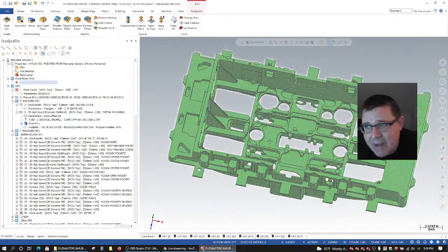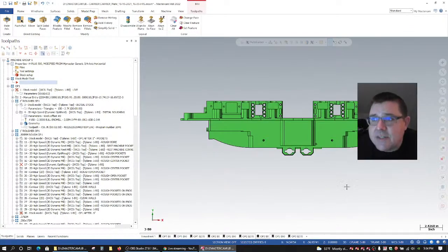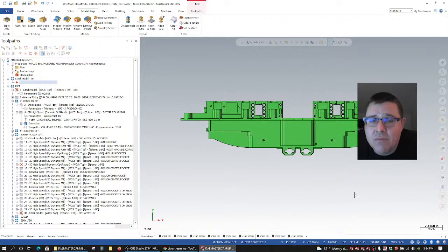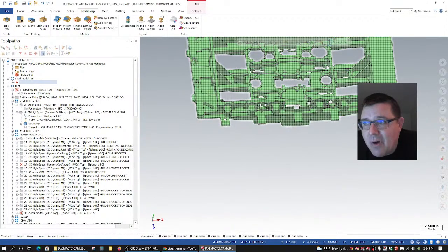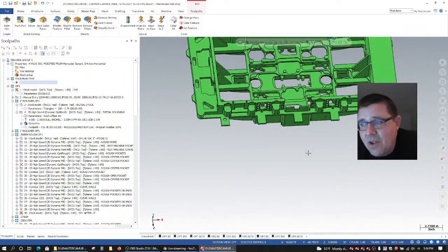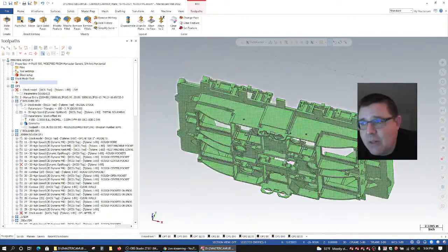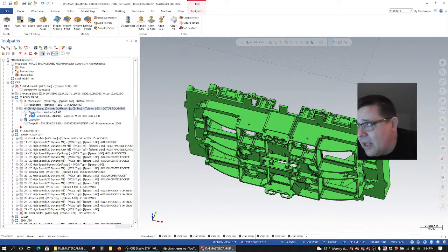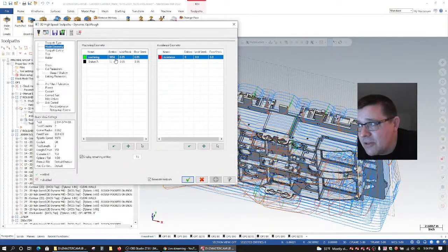What does this do for me in here? Okay, if my tool is coming from this view, this surface here, some of these other little surfaces, all of those are important. But anything that's deep on the back side here doesn't do me any good, and it just increases the calculation time.